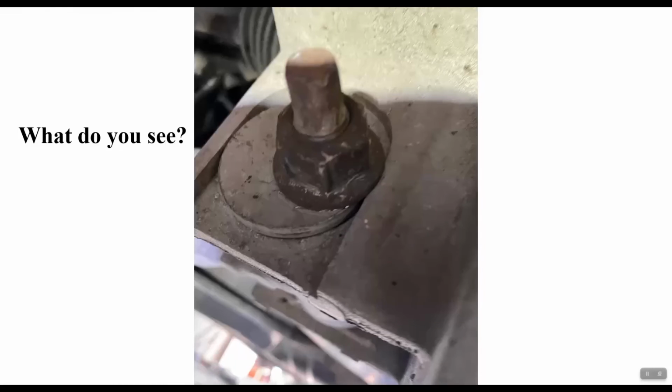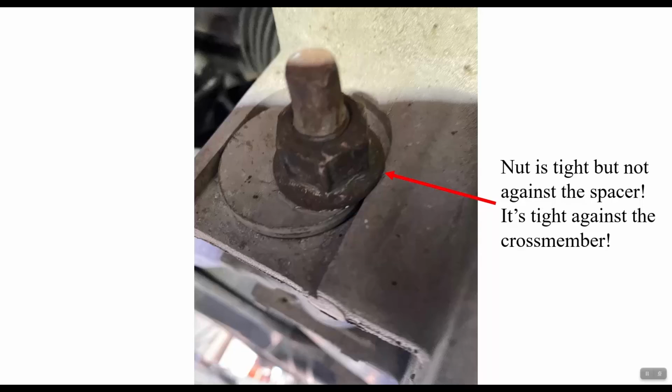Right, here is the fault. What do you see here? Okay, no prizes for guessing that. Okay, flange nut, eccentric washer there. Looking a bit closer here, notice the flange on the nut is not actually bedded down onto the washer. So the nut is tight, but it's actually tight on the frame, right there.